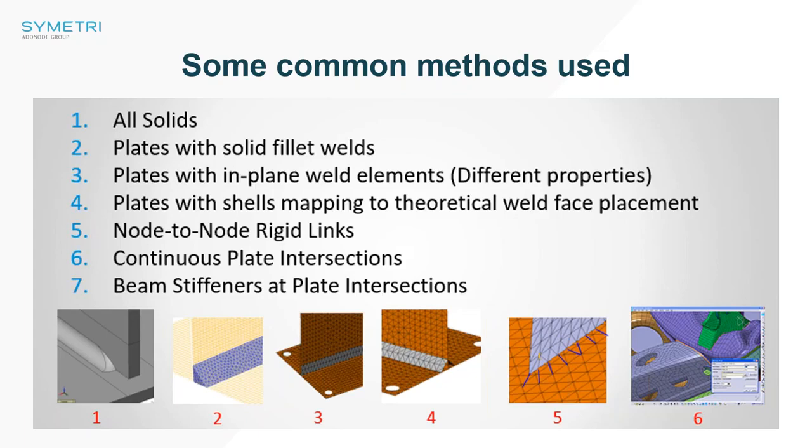Now, from my experience, people who do fabrications, which are primarily shells, won't even bother with the welds because it's just too much work and effort. I know that sounds lazy, but there is no real value. If there is an area where there are high stresses, then you could perhaps do a localized study. But what I'm trying to get to is there's no hard and fast rules.